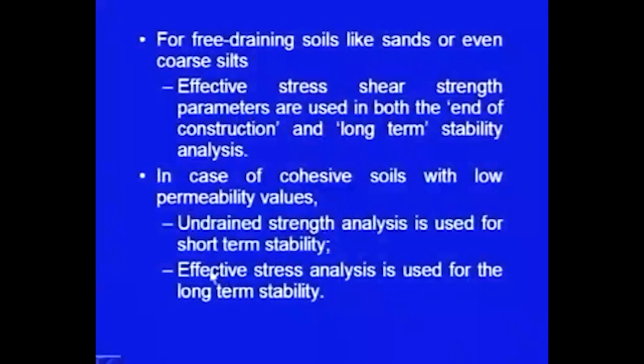Undrained strength analysis should be done, and for the long term stability, meaning after several years of the construction, the stability of the structure, of the embankment, has to be checked using effective stress analysis.